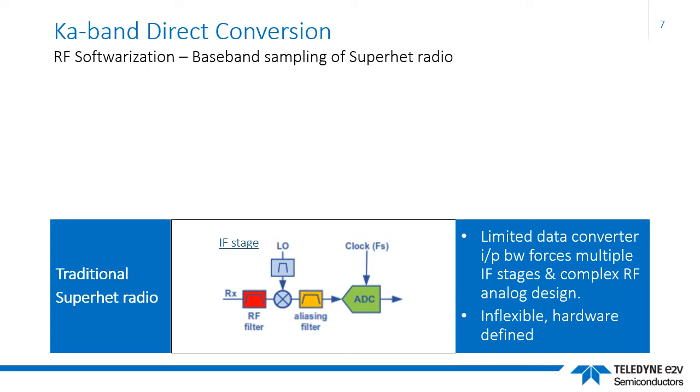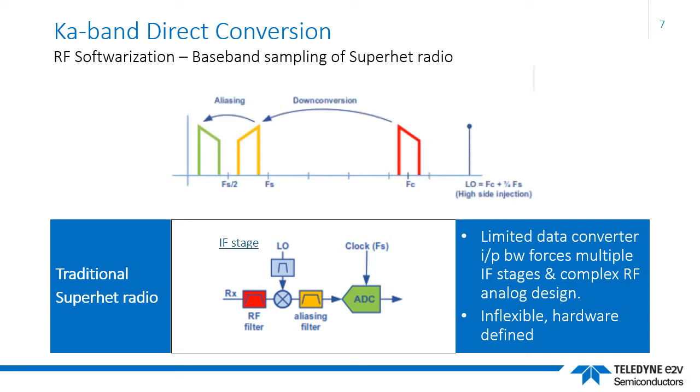The mixer performs a frequency translation, down-converting the band-limited RF signal to a frequency that falls into the baseband range of the ADC. This is a system that has predominated pretty much every class of software and digitally assisted radio system over the last few decades. It works well, but suffers from considerable analog circuit complexity in the signal chain and provides a very restricted range of programmable options. Furthermore, it's heavily determined by the hardware characteristics.